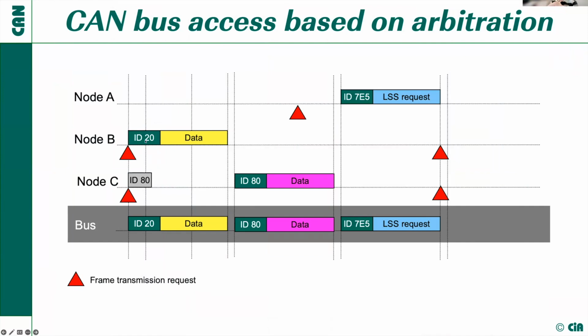So you have this arbitration mechanism, it goes directly via the bus. The frame with the lowest number, the highest priority, gets access, the other one is postponed. Furthermore, there exists the rule that CAN IDs should be assigned uniquely in CAN. This is true also for CAN-FD, as I've said, very strongly.